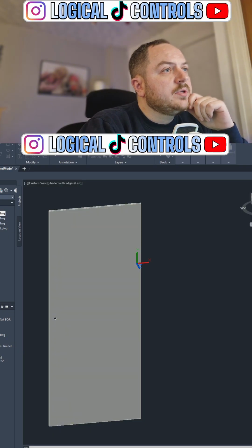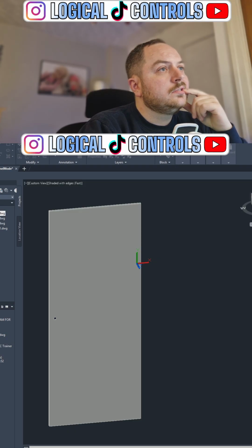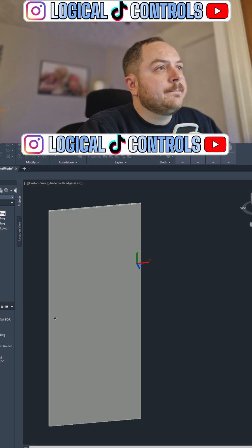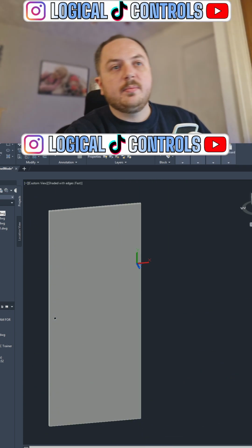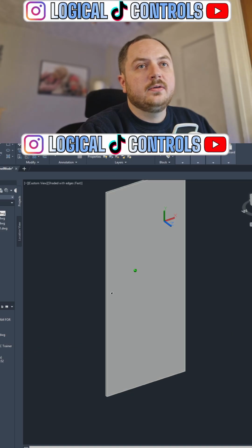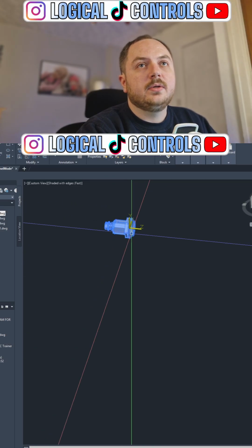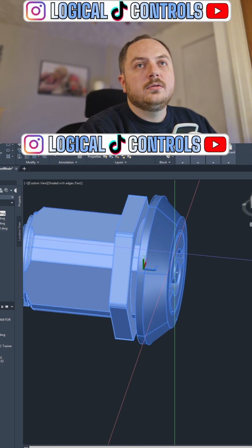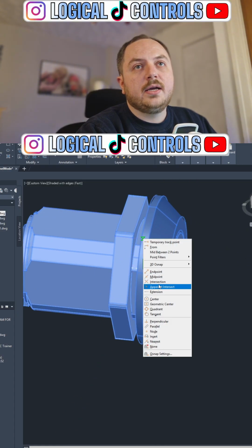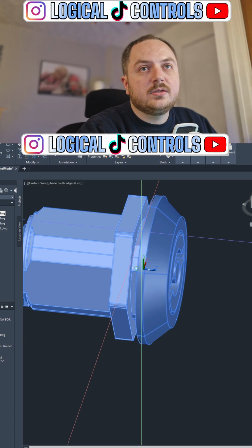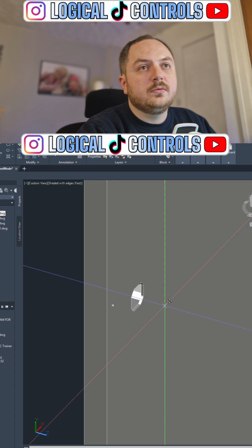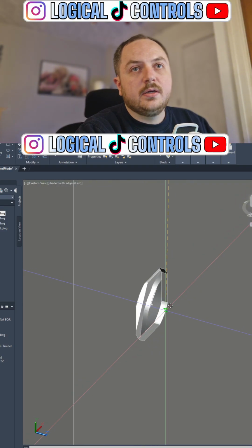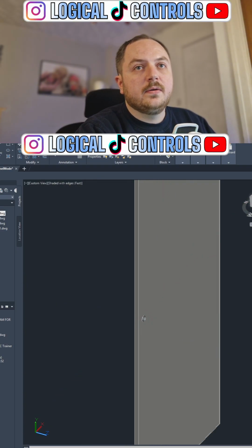I should have some MCA parts already, I think. MCA, drawings, locks. Quarter turn with insert, that sounds about right. I'd probably normally put a handle on a panel, like a door this size, but just for now. Where's that coming? There we go. So if I line up the center of this here, I can just smash that into, can you guys see that okay? Yeah. Center of there.